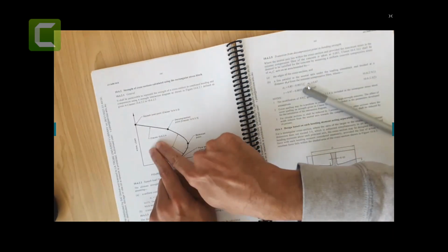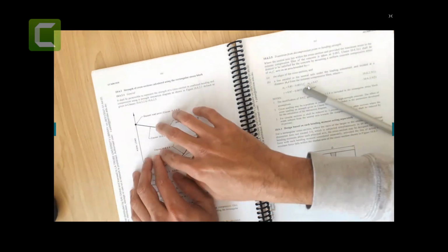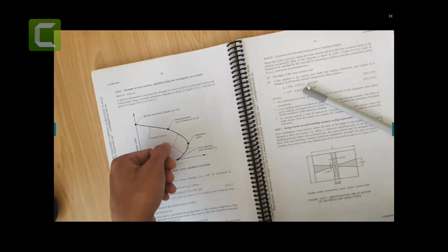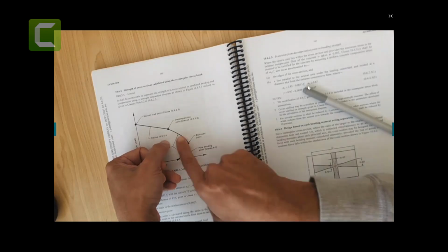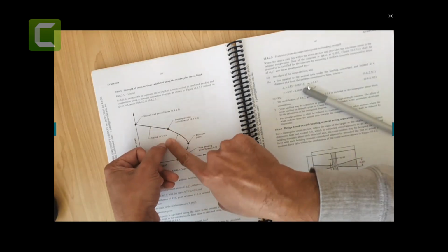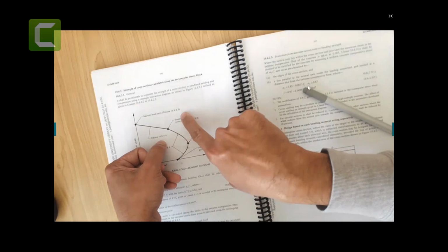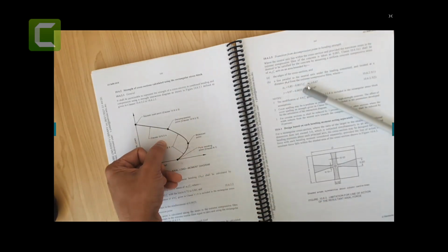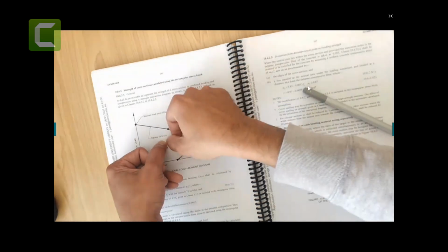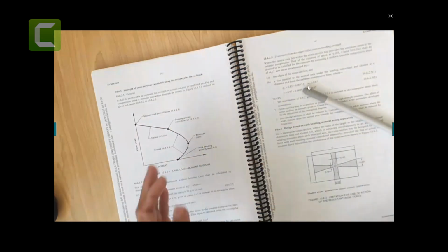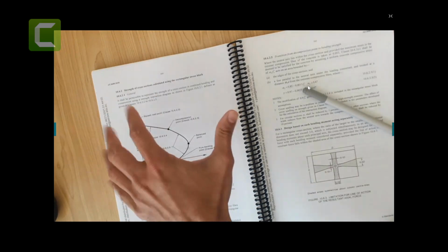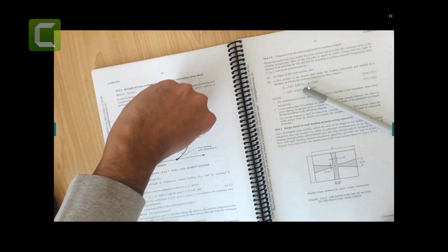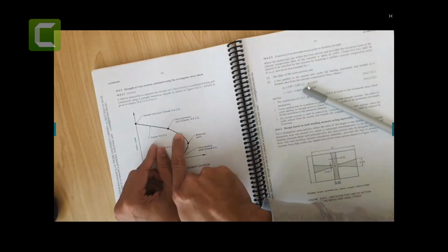One more thing, when you check your columns, let's say you know your design axial load and design moment. If your design axial load and design moment fall under this surface, your column is safe. If it falls here, you need to redesign, and generally redesigning means you need to include more reinforcement and so on. Look, this is not a magical curve. In the real world, you can't just say that if a tiny bit is sitting here it means it's failed.